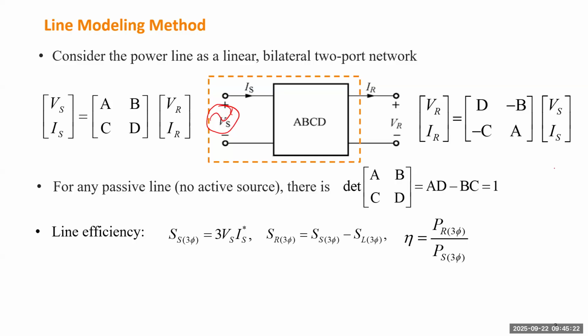Voltage regulation treats the source side and the transmission line as the equivalent source, and evaluates how easily the voltage on the load side can vary with the loading condition. So we know if VR is exactly 0, that's the ideal source. If VR is a very large positive number, it means the voltage can change largely if you increase the current.